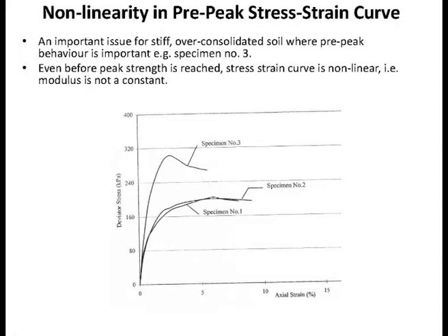When I model a soil like that, a lot of people, including people like Richard Jardine at Imperial College, will just use Mohr-Coulomb, and on the elastic portion they just fit in a curve that looks like that. Now, if you are using the hardening soil model, I think there is some facility for you to reproduce this.